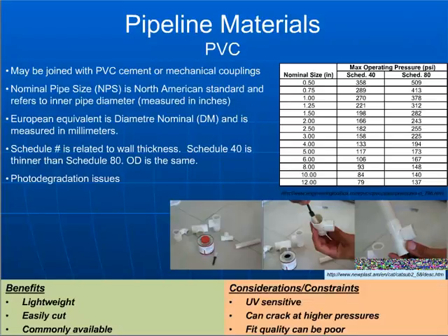There's often some confusion about the outer diameter of the pipe versus the inner diameter of the pipe, and it's very easy to get the wrong fittings that may not work if you've specified the outer diameter and the plumber thinks you're specifying the inner diameter, or the hardware store thinks you're specifying the inner diameter. So just make sure that you have both a good idea of what's available locally and then how the locals refer to the different pipe sizes and different grades of material.